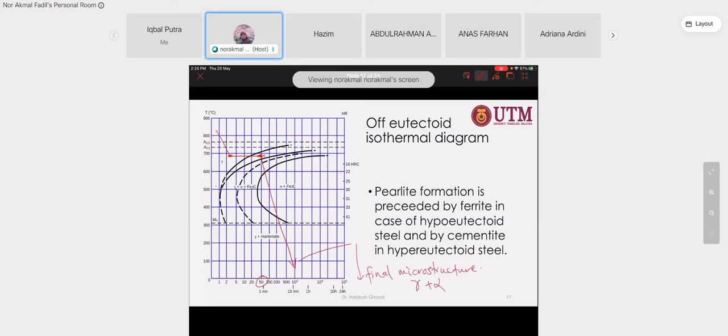All right, gamma plus alpha. So let's think. If we refer back to the phase diagram, this is gamma. This is alpha plus gamma. This is alpha plus cementite. And this is gamma plus cementite. What temperature is this? 727 degrees Celsius. So now you quench to room temperature. How can you obtain gamma?